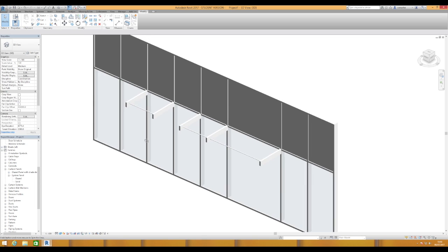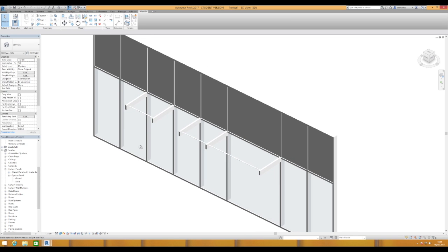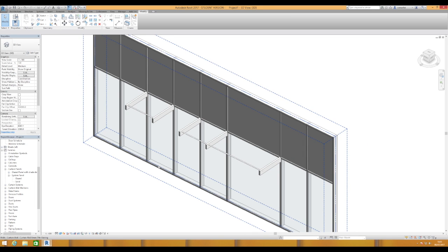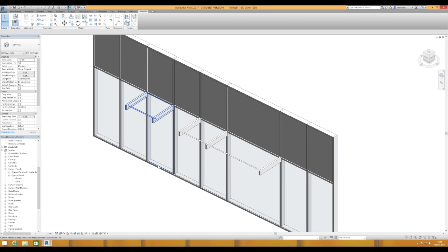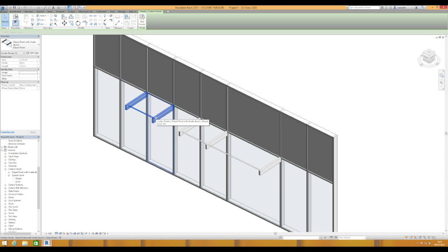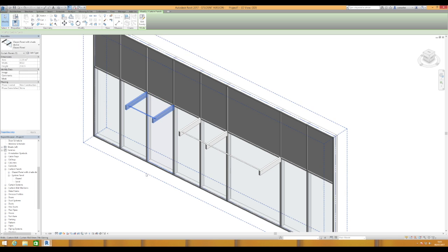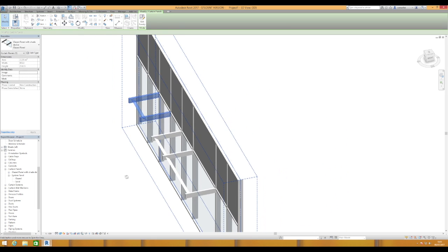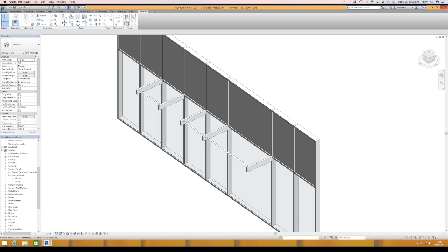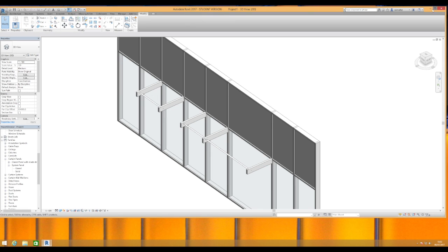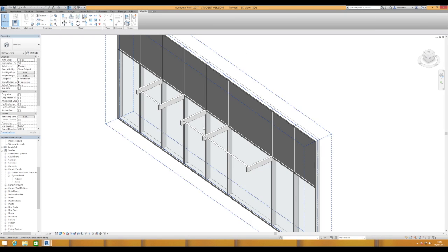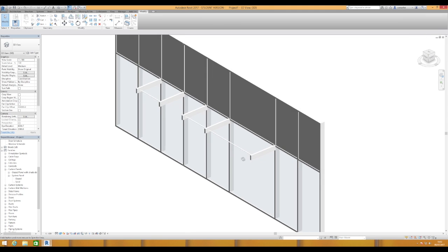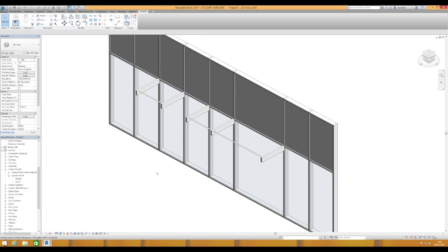So you can see how now we can have 3 different sorts of materials in this one system, this one curtain panel. The 3 materials we've got is the glazing material, then we've got the louver support material, and then we've got the louver material, and they can all be assigned to different materials the way we've done this. Okay, I'll just fix that up. Okay, now we'll just continue on now and just fix up the final geometry to do that sunshade device.